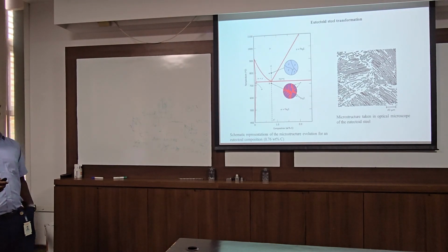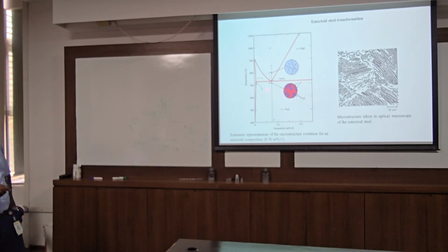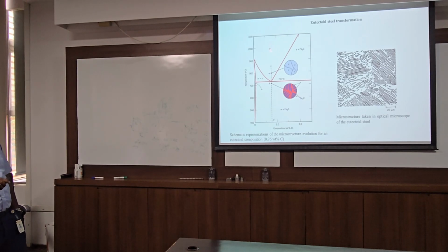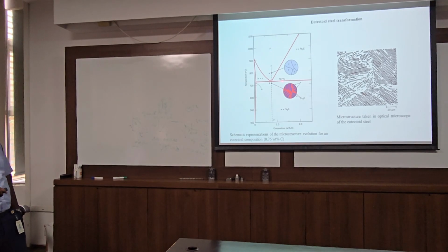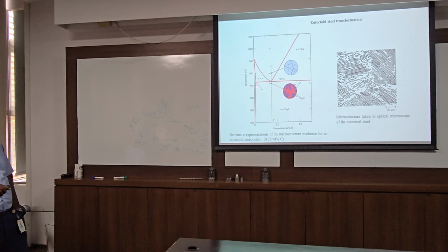So similarly, like a very low melting point of two solids, that is eutectic. Similarly, eutectoid also. In this, the phase is more stable down to a lower temperature, 720. So if I take this side, what will happen if I arrive at 800 degrees centigrade, it starts transforming to solid. Similarly here also. But when I take exactly this composition of the steel, suppose I choose this steel of X percentage, it's exactly the eutectoid point. So I will get the existence of a single phase of gamma up to 727 degrees centigrade.